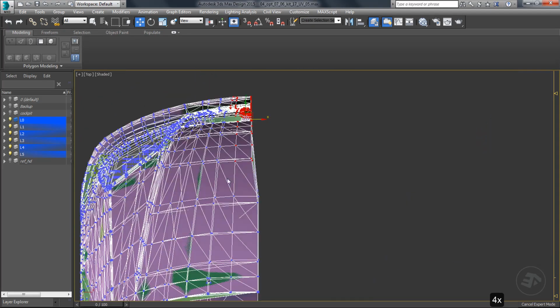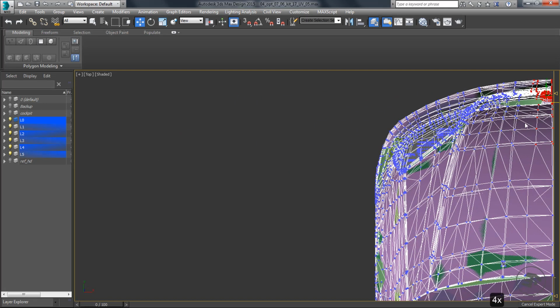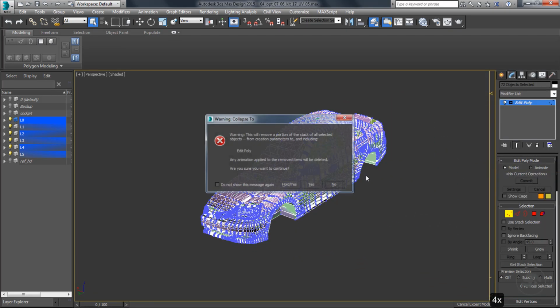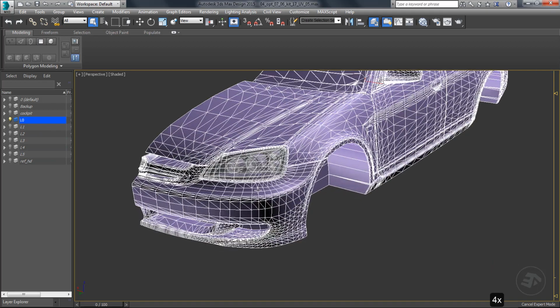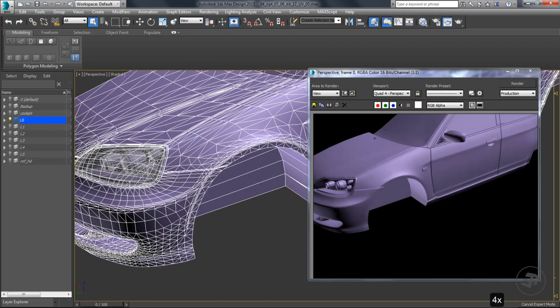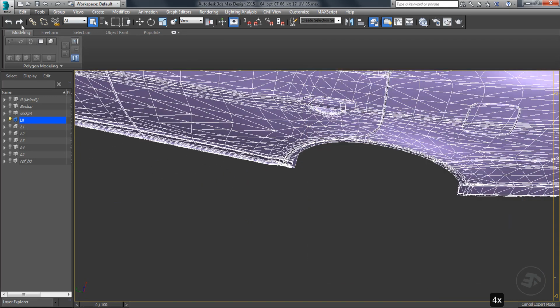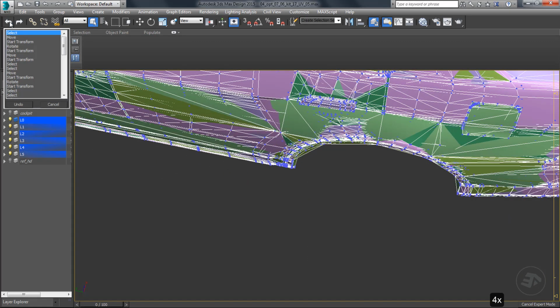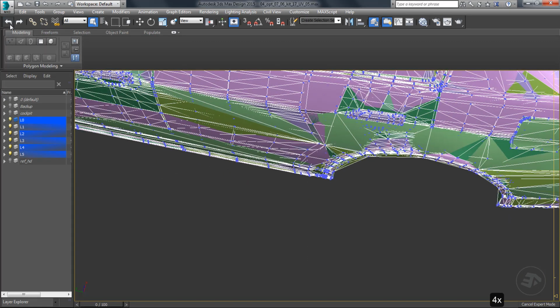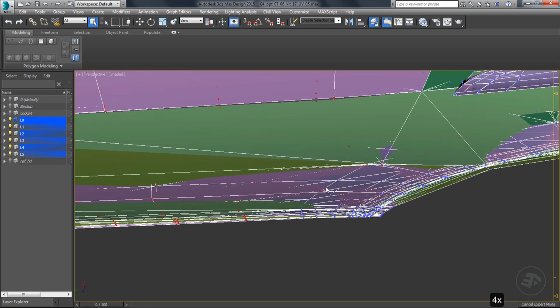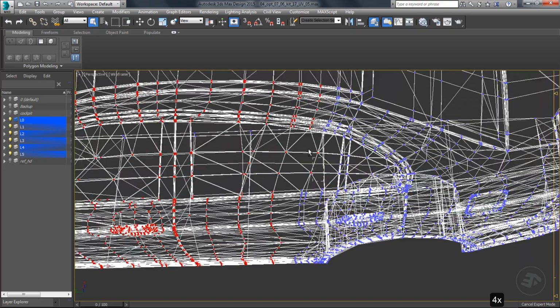Although this might look easy, it's not once you try it by yourself. The Move tool is not your first choice when it comes to correcting such geometry misalignment. You cannot use the Move tool to move the vertices or the polygons of the front fenders to extend them. If you do this, you will disrupt the curved surfaces that extend from the front fender to the front bumper.